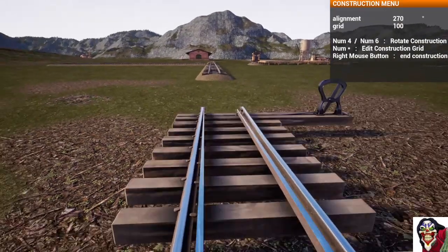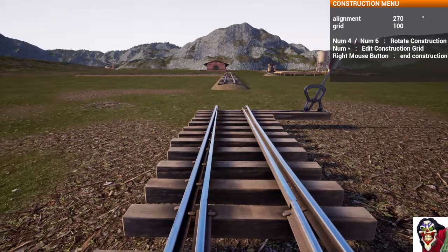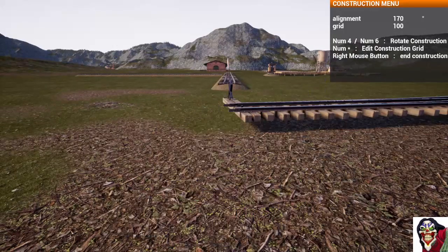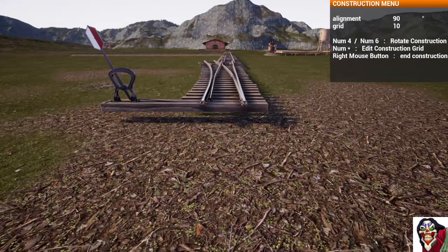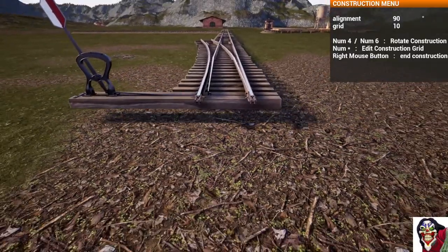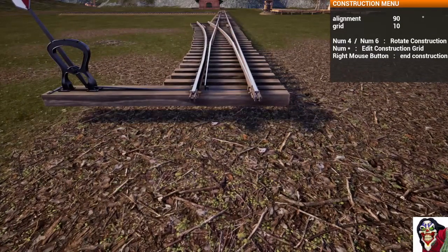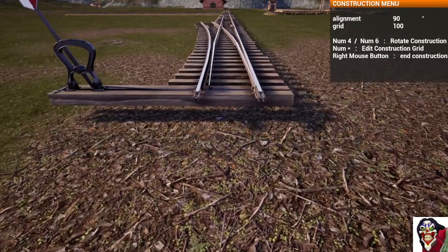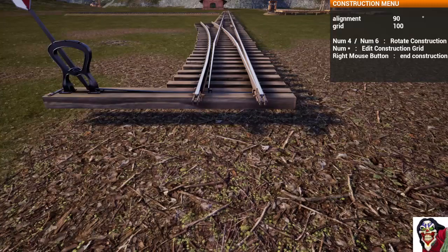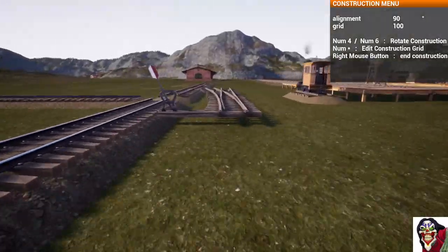and of course, because I'm facing the wrong direction, you can spin the switches, which is something that you never used to be able to do in the old system. You can spin the switch round to be 90 degrees. We'll line it up here somewhere close to where the end is. And if we put this on snap to 100, it will actually snap to the point of where that line is. And you can see it has left a short gap, but that's fine.